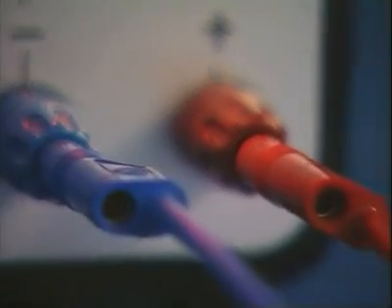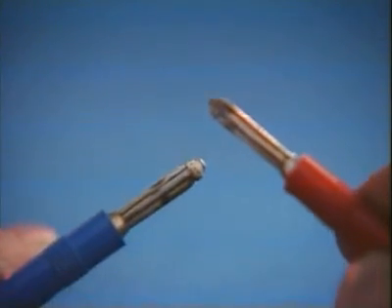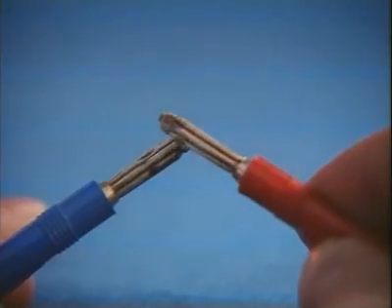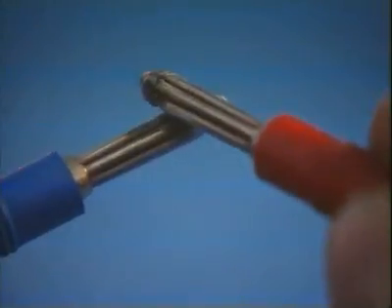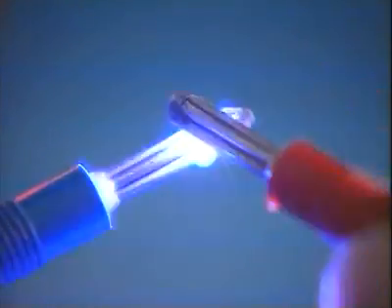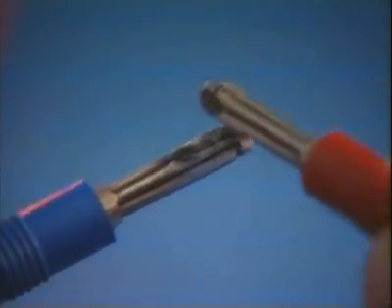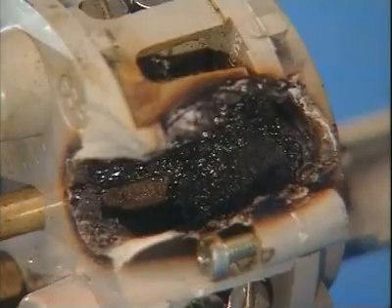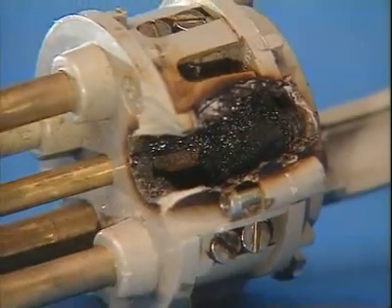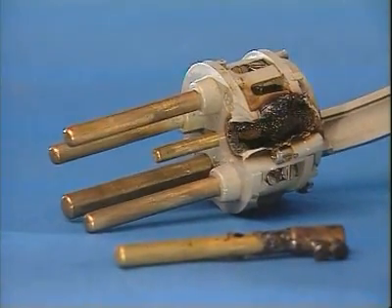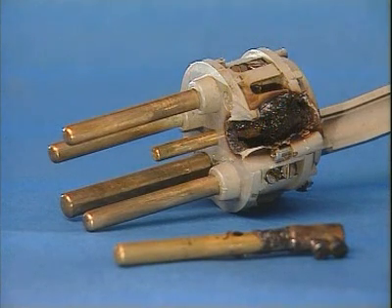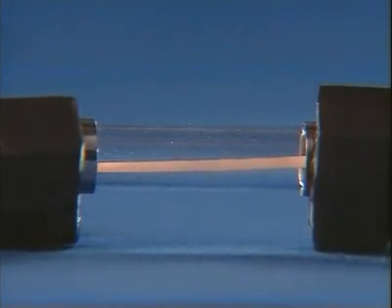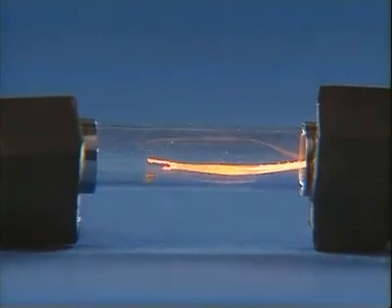And here is a phenomenon that everyone knows, the short circuit. What happens exactly? If in an experiment we connect both poles of a voltage source directly, an extremely large current flows because there is no resistance. The result, extreme heat which leads to melting of the conductor or other damage. The solution? Fuses are integrated into electrical circuits. The fuse then interrupts the current flow and prevents further damage.